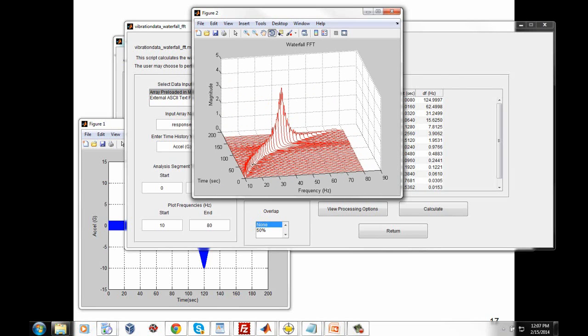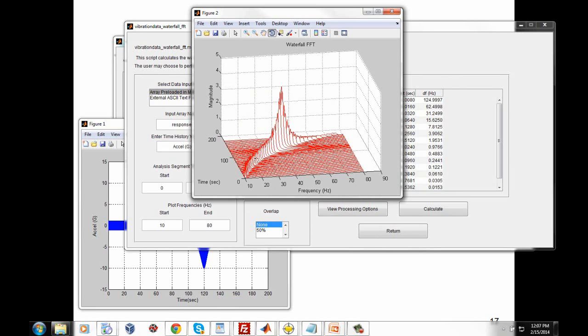So down at the lower frequency end, we've got this unity gain thing going on. Then as our excitation frequency starts to approach our natural frequency, we ramp up to our resonance case here. Then as we get past resonance, the response is decreasing. What's happening is our single degree of freedom system, in some sense, is acting like a mechanical low-pass filter. So it really wants to filter out, or attenuate, this high frequency energy.